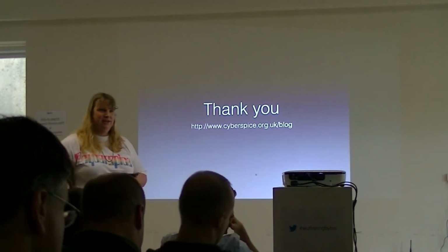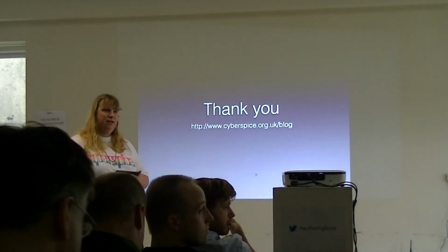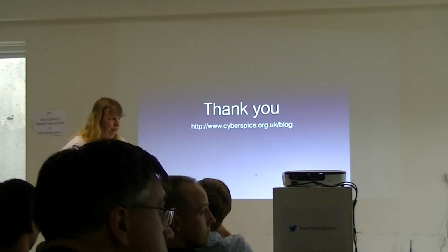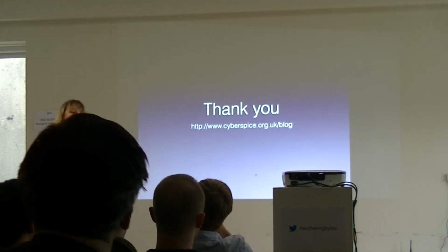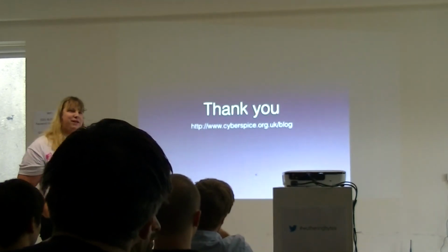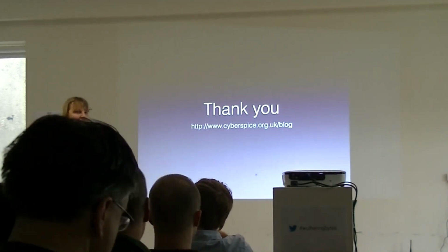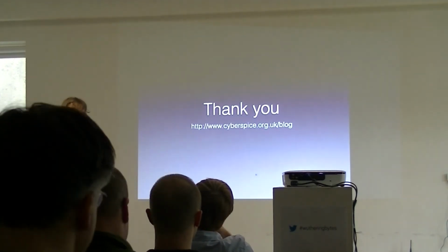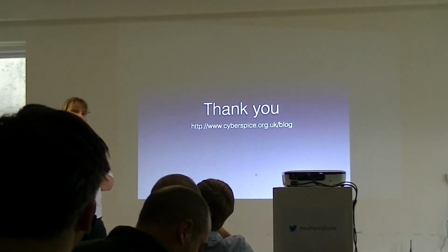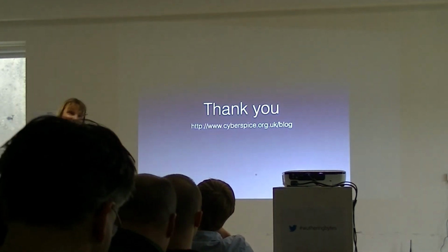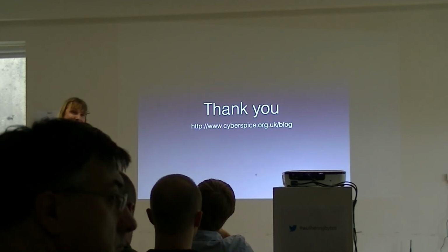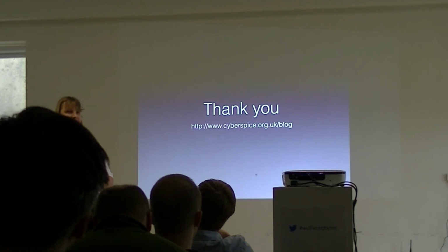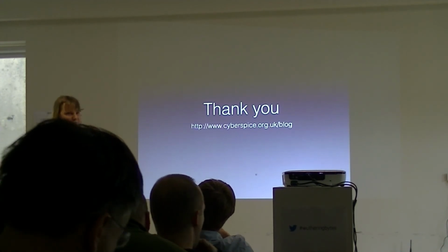Back on serial I/O. Okay, why is MOSI connected to MOSI and not MOSI connected to the output? To annoy engineers who build a PCB and then find it doesn't work and find that they've actually wired the two up the wrong way around. It's because it's called master out, slave in. So even if you're on the slave, it's still the master out and it's still the slave in. But that is one of the common bugs that you find in the hardware, that people have gone and swapped them. That's a mystery the universe solved for me.